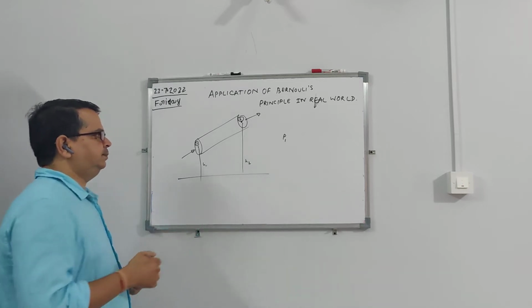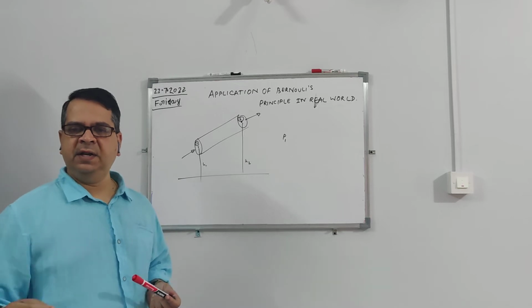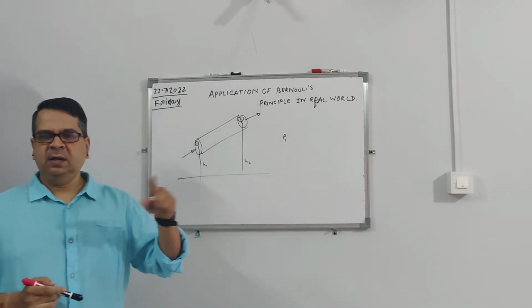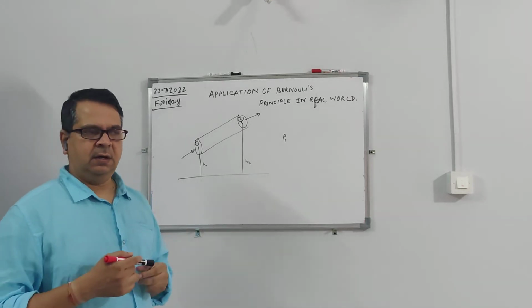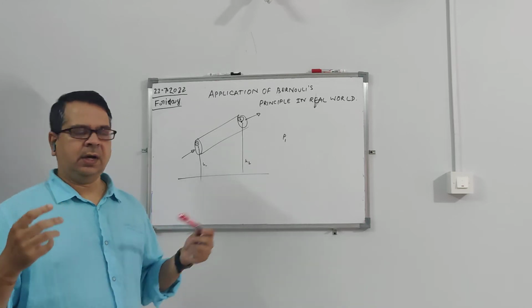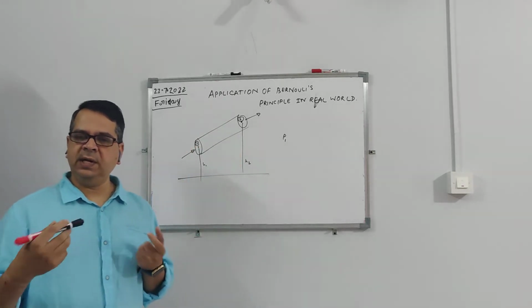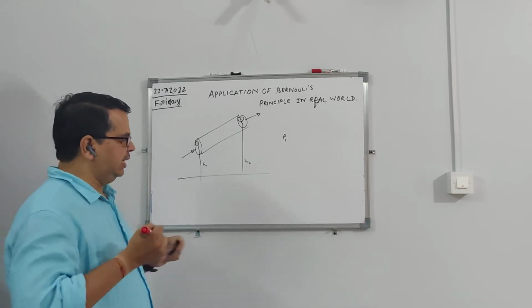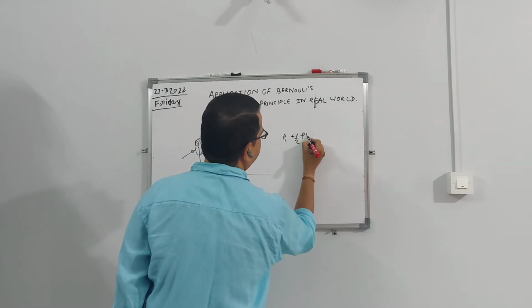Here the unit is very important. When you are adding different things, everything should have the same unit. So if this is pressure, the other two terms, like the velocity head, should also be in units of pressure or Pascal. I am not deriving it; that is just plus half rho V1 square.